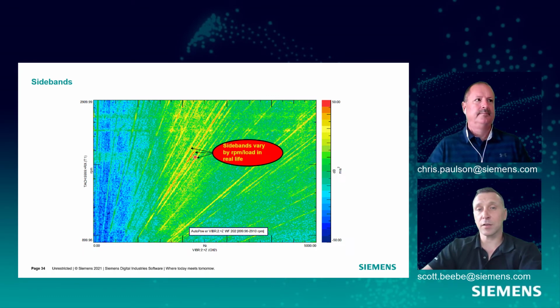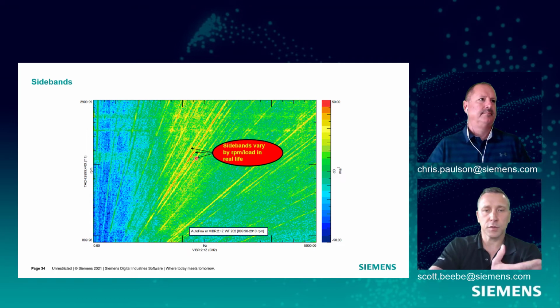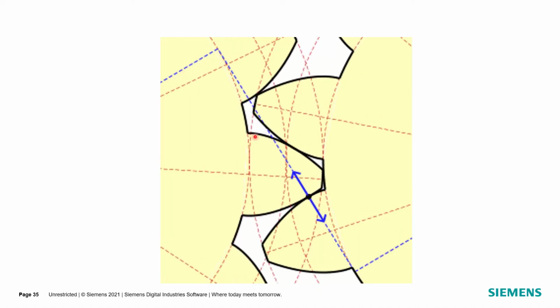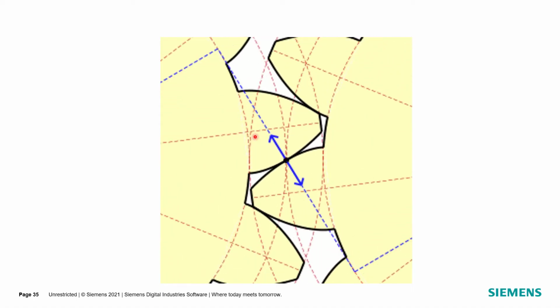Here, looking at this color map, you can see that the plus or minus second order is more prevalent. So maybe the issue to look into, if you're trying to improve this transmission error or the performance of these gears, would be to look at the oblong gear to see if there's something that could be done on the manufacturing side. I think this one's you, Chris.